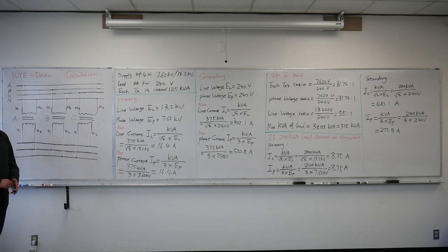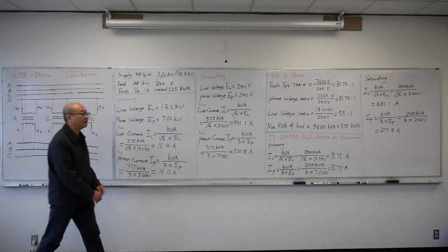If you remember the phasor diagram we showed you and the connection summary, here's the way we connect it. Phase A transformer, H1 connects to line A, H2 connects to neutral. Phase A transformer, X1 connects to line A, X2 is going to connect to line B. Same goes for the phase B and phase C transformers. In this connection, the high voltage side is going to lead the low voltage side by 30 degrees. So that's the phase displacement.